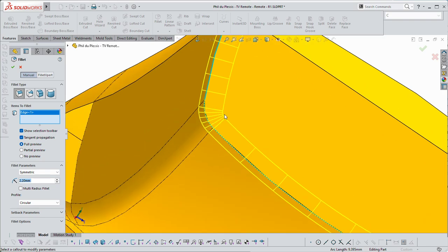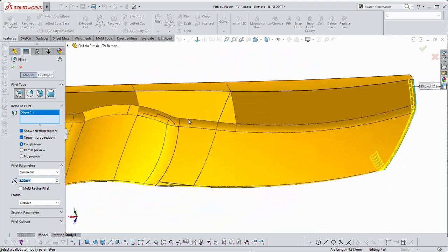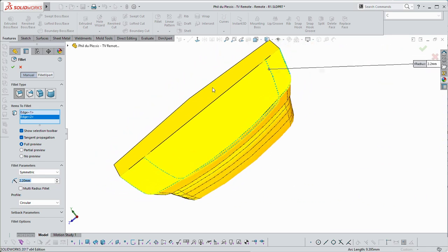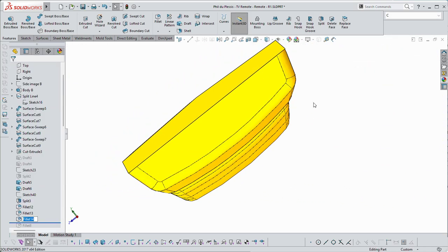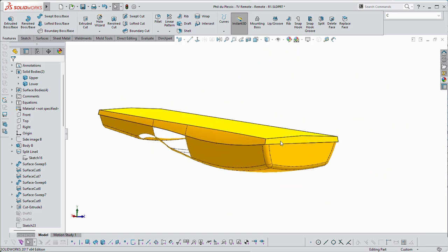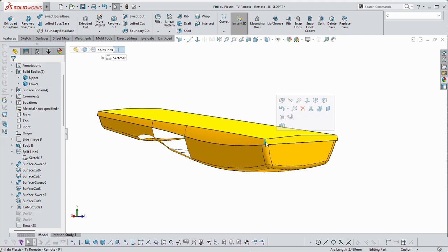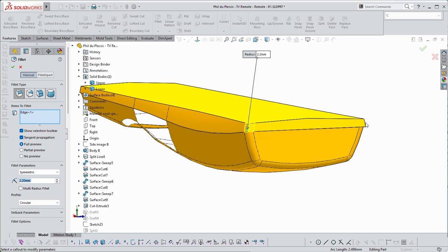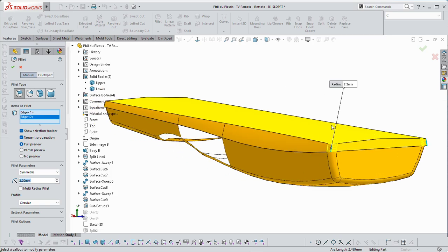So you can see from this that I now have a four-sided cap. That means that I've got two sort of curves, an inner and an outer. I'm going to select this other end here. It's going to do the same thing. Say OK. There we go. Okay, so that's fillets on the bottom face. And now let's do the same for the top, sort of bottom half. And so this fillet must echo that fillet, in that it must be the same size because they're going to meet at a parting line.